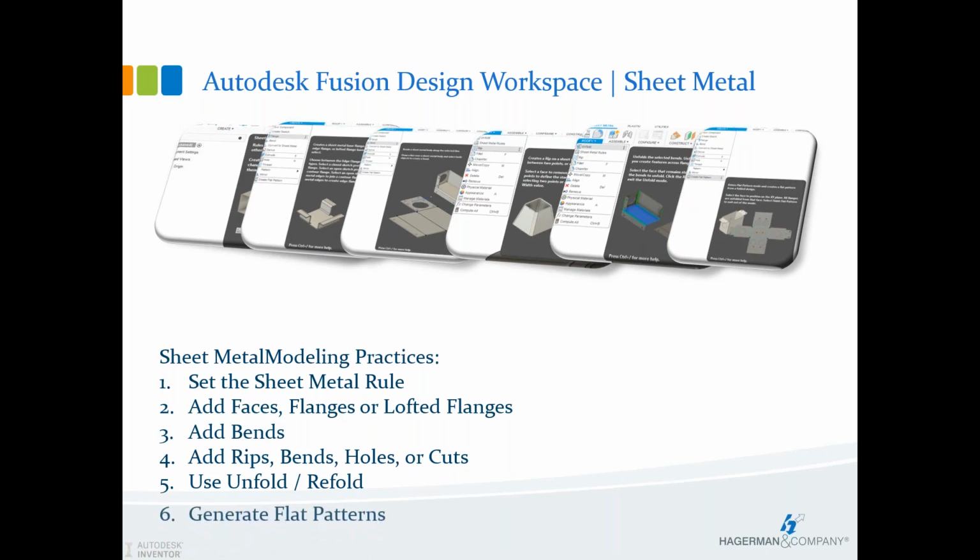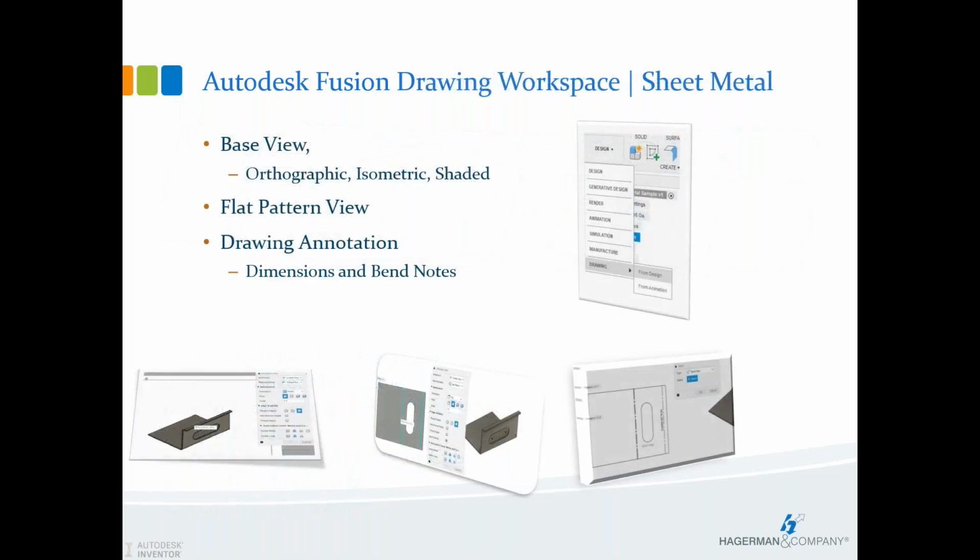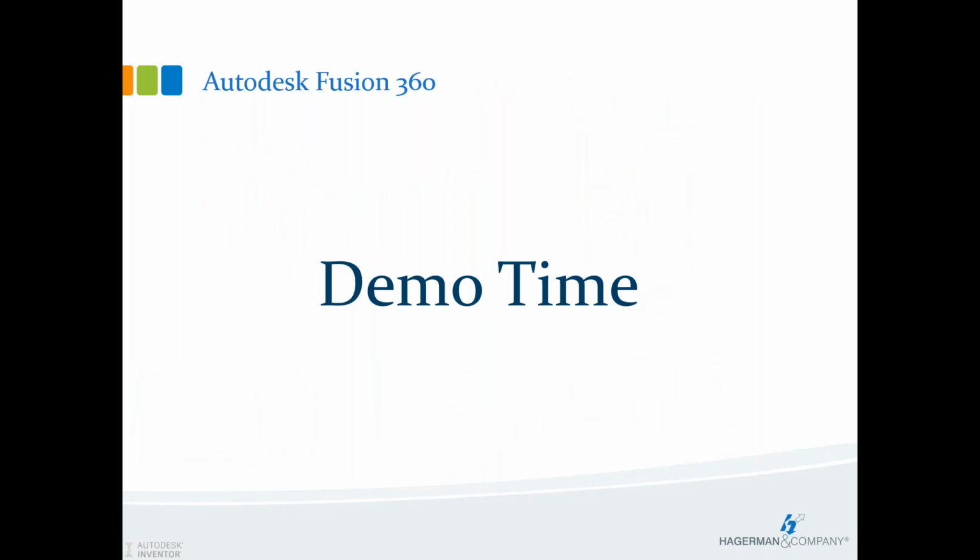And then finally, as far as the model is concerned, we'll look at how to generate the flat patterns, how to pull out a DXF file, and from there we'll move into the drawing side. Just a quick overview of placing those views, being able to place that flat pattern view, as well as adding dimensions and bend notes and some different settings about the view itself, whether we want to see the bend extents, and so on and so forth.